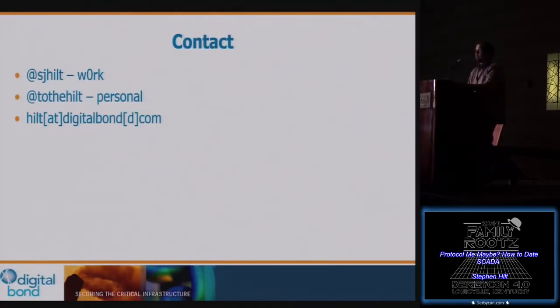Yes, correct. So there's a lot of testing, as we recommend, once again, not scanning the internet. There is an inherent risk to doing that, but without identifying it, you won't know it's there. Somebody else will. Even the latest malware, Havex, that attacked specifically targeted ICS, you'll notice they were actually using some of these protocols. They were searching for Ethernet/IP, Siemens, I think they were doing Modbus. I saw one report as well. And then OPC. So the bad people are already out there searching for it.